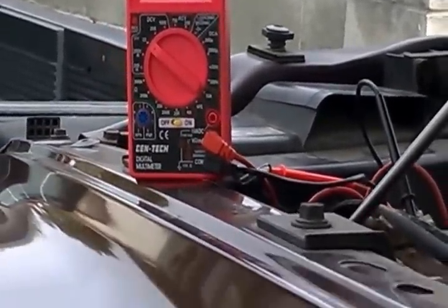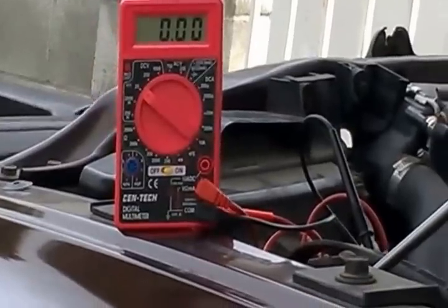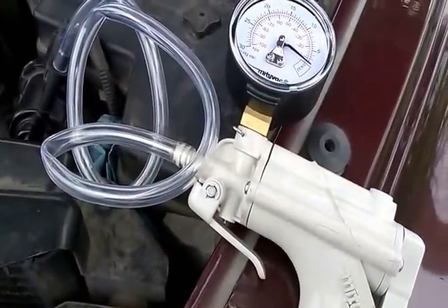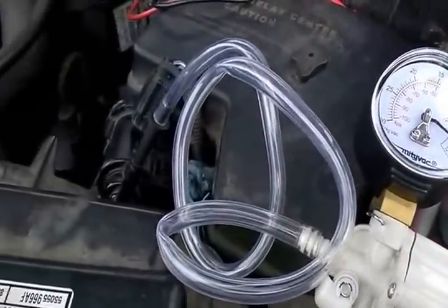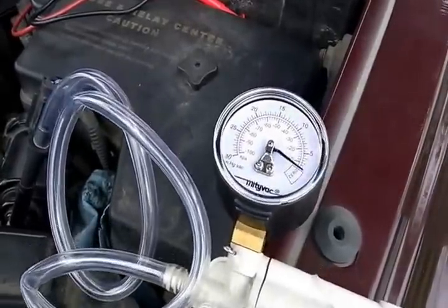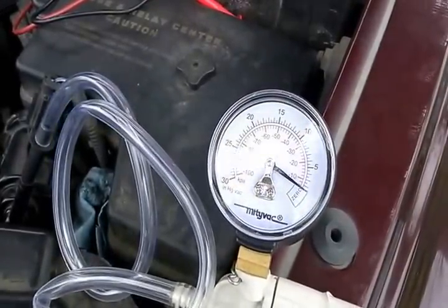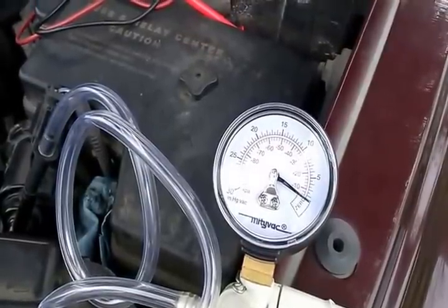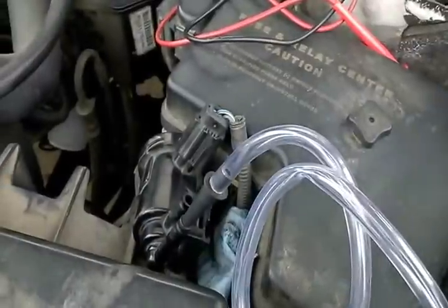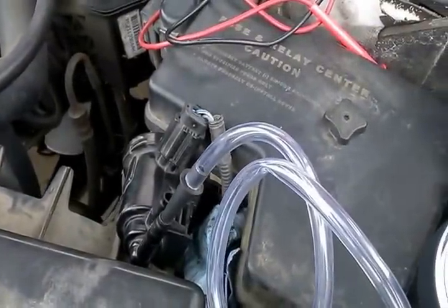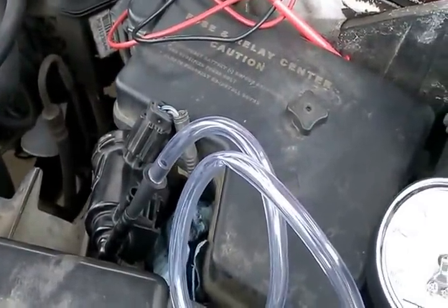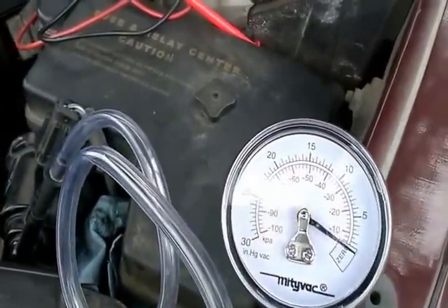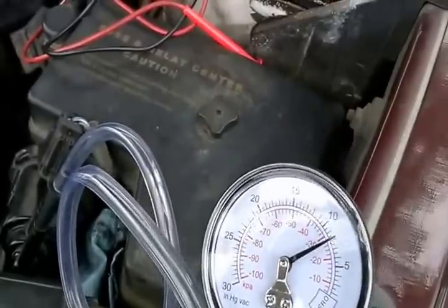So the next step is to do the vacuum test on the solenoid to see if it's holding vacuum. Alright, so on this test, I'm going to perform a vacuum test on this purge solenoid. The repair manual said to apply 10 inches of vacuum, and this vacuum should hold 15 seconds or more. If it doesn't hold vacuum, it means the internal side of this solenoid is basically bad. The valve seal is not holding vacuum anymore, so it's leaking through the seal. So I'm gonna apply the 10 inches and see what happens.